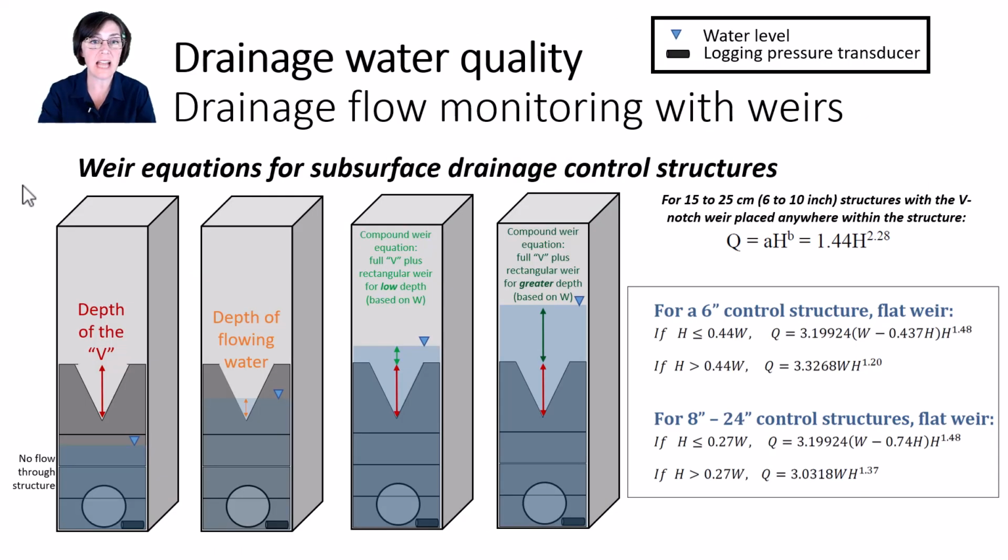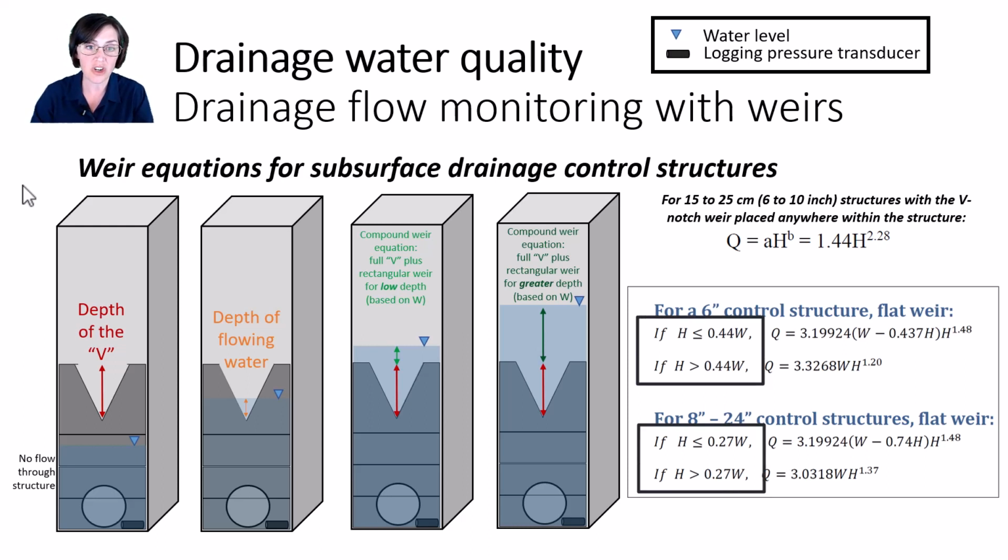But we're not done yet in those scenarios because we need to know when to use either one of these other two equations to add on top of the V equation. The decision point here is based on the width of the structure and the height of water on top of the V.